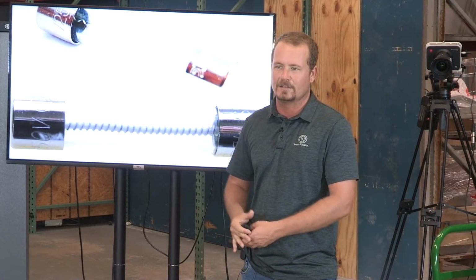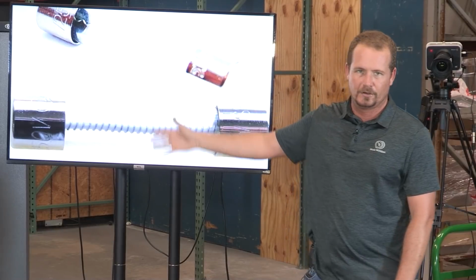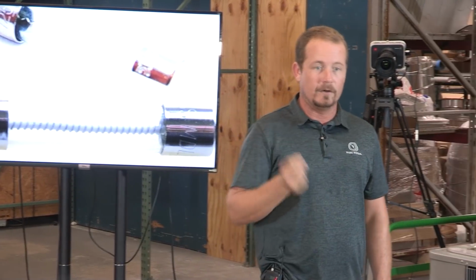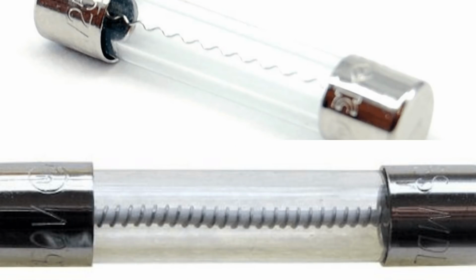Now, I'm not saying that's always universally how they're going to look, but you have some fuses that when they get to their rating or above their rating, they're going to blow really quick. And you have some that are designed to not blow quickly on purpose.